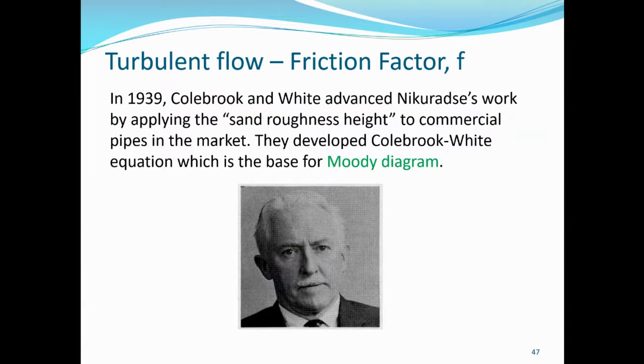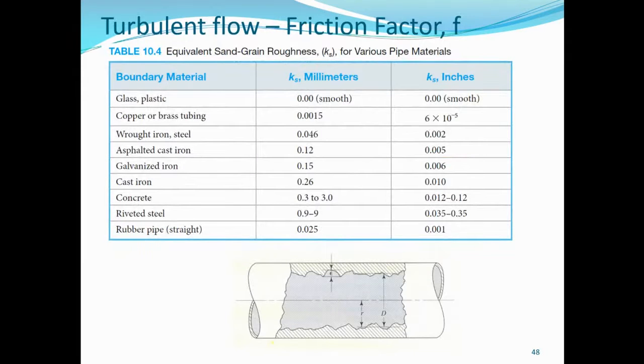Now in 1939, Colebrook and White advanced Nikuradse's work by applying sand roughness height to commercial pipes in the market to develop what is called the Colebrook-White equation, which is the basis for what we are going to explain as the Moody diagram. So this is for commercial pipes.